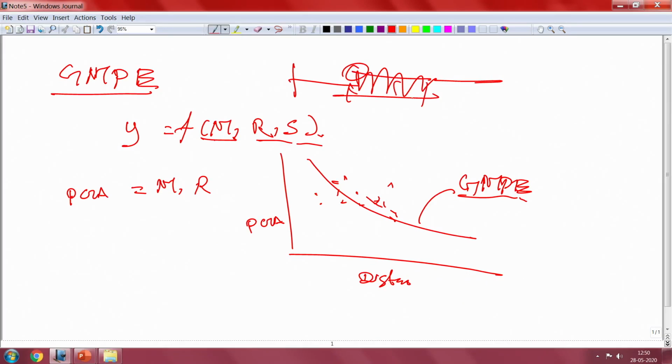So the next parameters are the frequency domain parameters. This means whatever time history data we obtained from the seismometer or accelerometer should be converted into another form. It will be transformed into the frequency domain, and from that you will estimate some parameters. Those parameters are called frequency domain parameters.